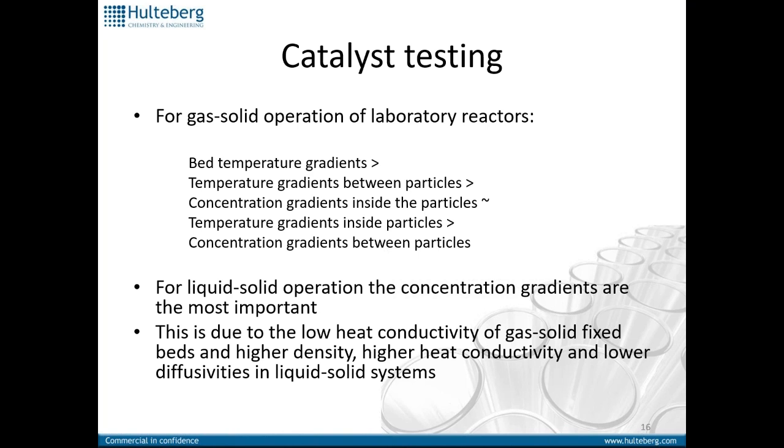First of all, for gas-solid operations, there will be most severe gradients with respect to temperature in the entire bed, because the heat conductivity of inorganic oxides is quite poor, and that's normally what we have as catalysts. And also the heat conductivity of the gas is low. So if there is reaction heat generated somewhere or indeed consumed somewhere, it's likely that it's not transported somewhere else. So in the bed, the temperature gradient is believed to be the one that has the largest influence.